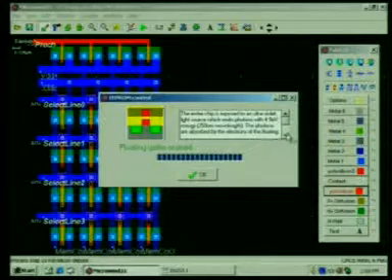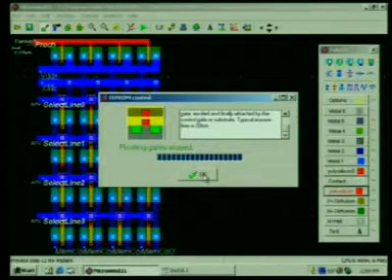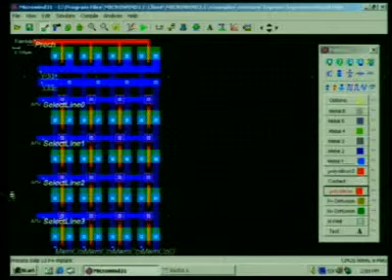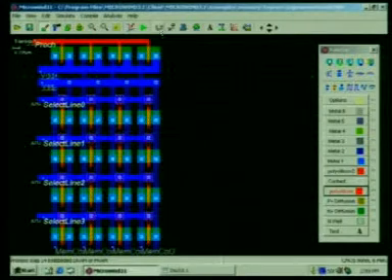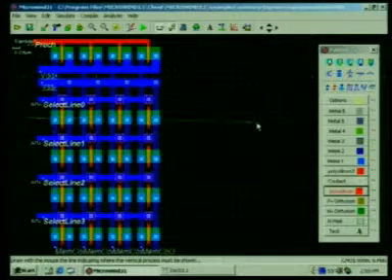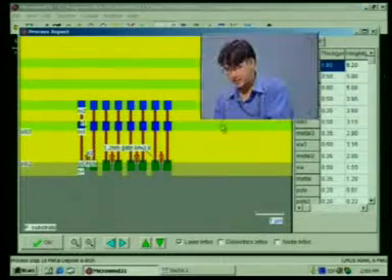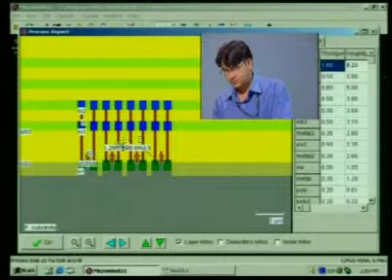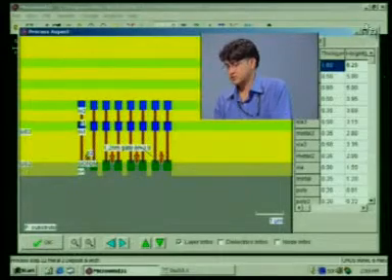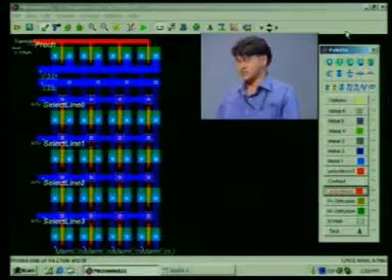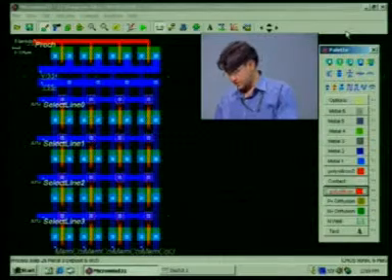Okay, it will take some time and this data will be generated. You can read out that. Okay, see this, now all the data is erased. Now, you have to select the proper word line, proper bit line. After that, you can dump the binary code. Now, all are zeros.